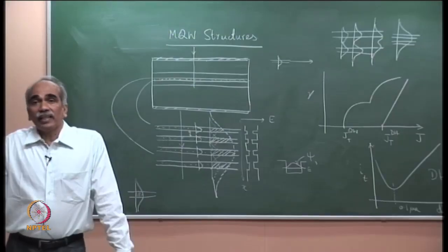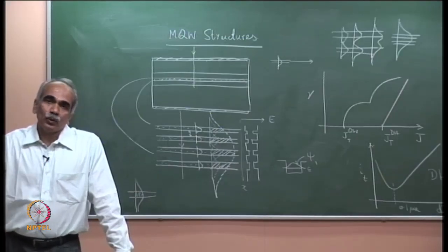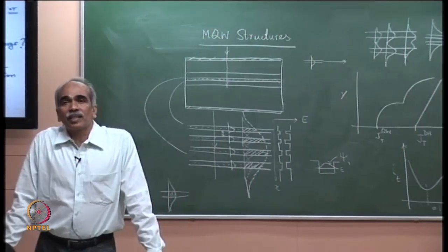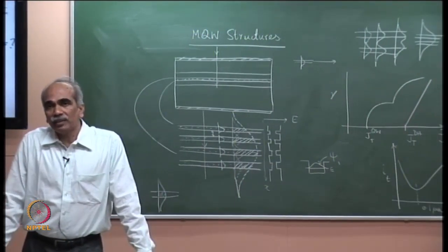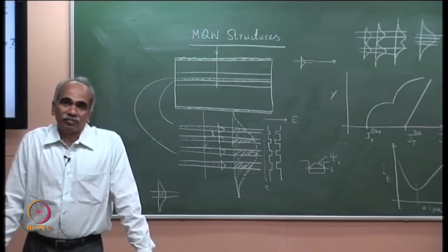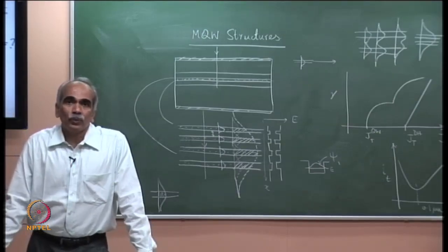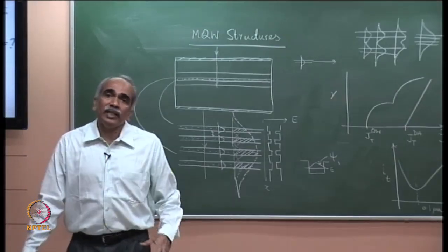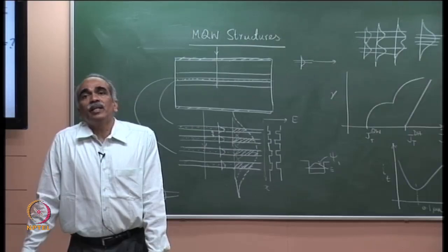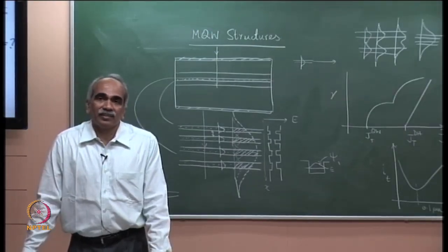It is very clear that an AR coating, as the name indicates, is an anti-reflection coating to block reflections coming from the ends. If the reflections come from the end, there will be feedback from the ends and the cavity will also form a Fabry-Perot cavity, and therefore, there will be allowed resonances at those frequencies. To avoid this and to select only one frequency that is selected by the grating, we need anti-reflection coatings at the ends. That is the answer. I hope it is clear.